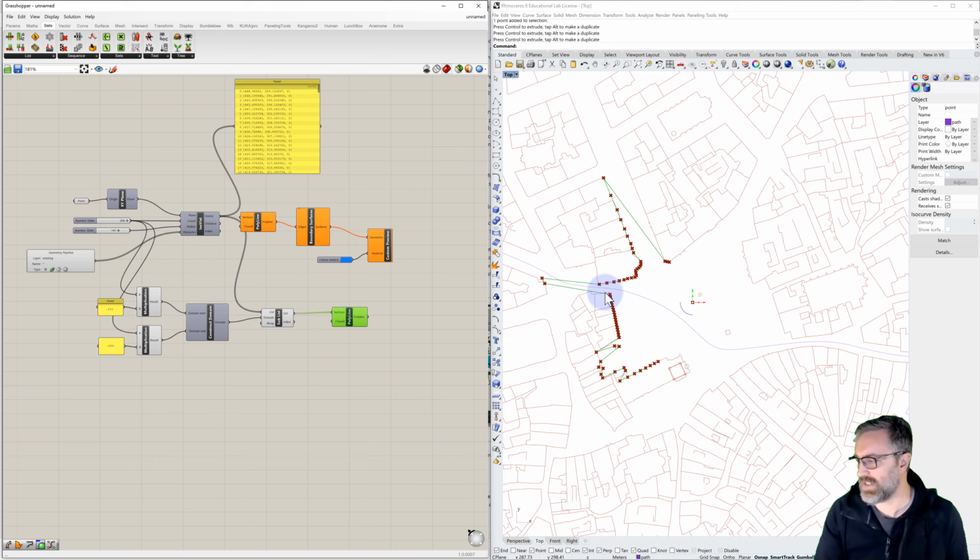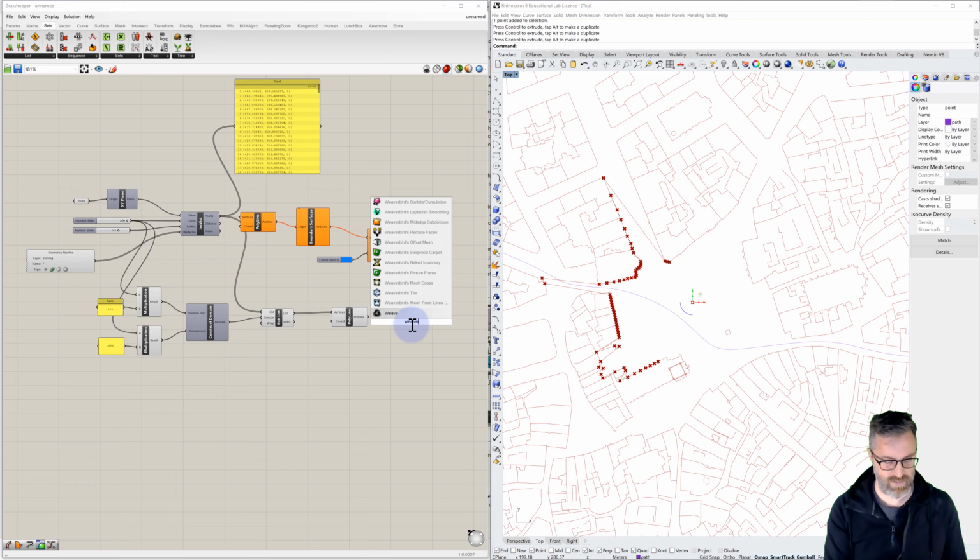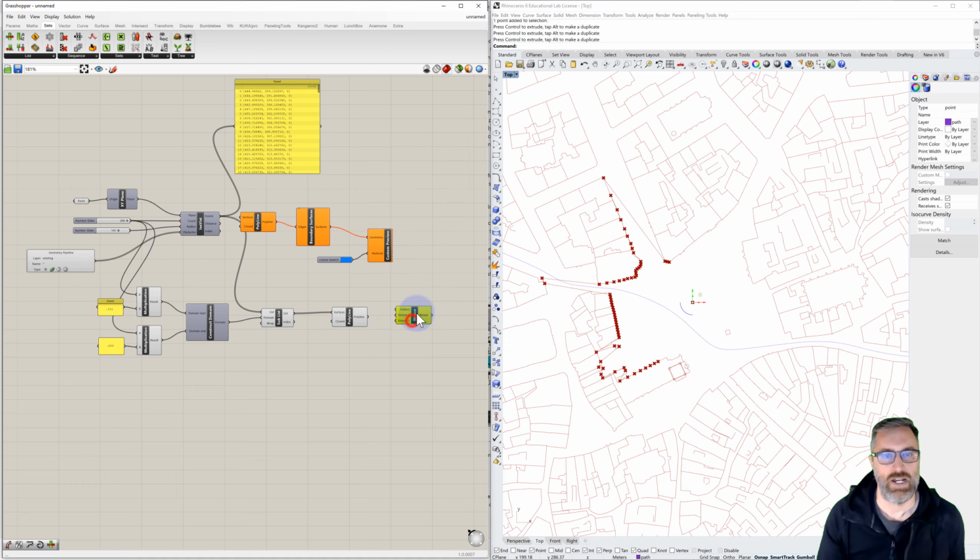And so the way that I did that is I created a weave, and we used this in a previous tutorial. And what I wanted to do was weave together a pattern. Mouse over, we can see the pattern is 0, then 1. And so that pattern will be my points. Let's see, the sublist will just be our point, will be item 1. Our sublist will be the other point. So we've woven those together.